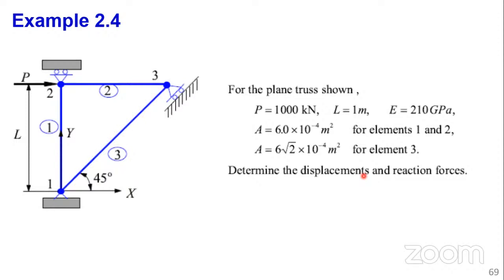So you can see node 3, in this particular case, the orientation. You can see how the boundary condition is oriented. If this was to move, because this is a roller support, it moves in this direction. So you can see these are a little bit complicated boundaries. But first things first, you don't have to worry about that because that's about the boundary. At this point, we say boundary condition of any quantity, whether it's force. Remember, boundaries define the displacement and they also bring about the reactions.